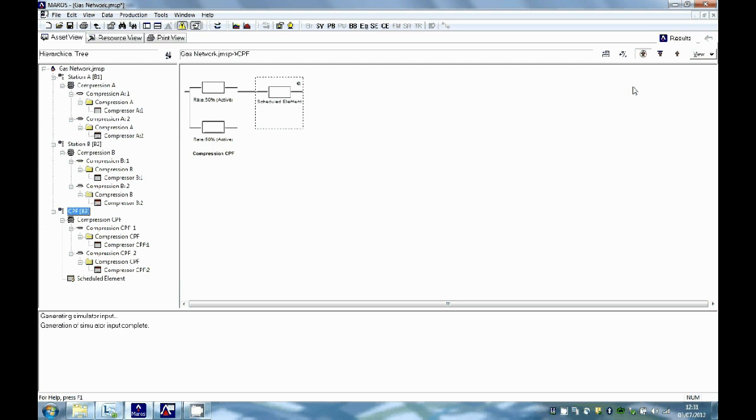Normally the production requirement defined by the sales profile is less than the production volume the system is capable of, defined in the normal profile. During normal conditions, the system produces at a rate defined by the sales profile. If an event occurs in one part of the system which prevents the sales profile requirements being met, the system will boost to recover. And the third boosting option is the user-defined boost, which is selected by pressing the third button. If user-defined boost is selected, then an additional data grid tab called Max will be available. So we want to select the recovery boost and run the model.